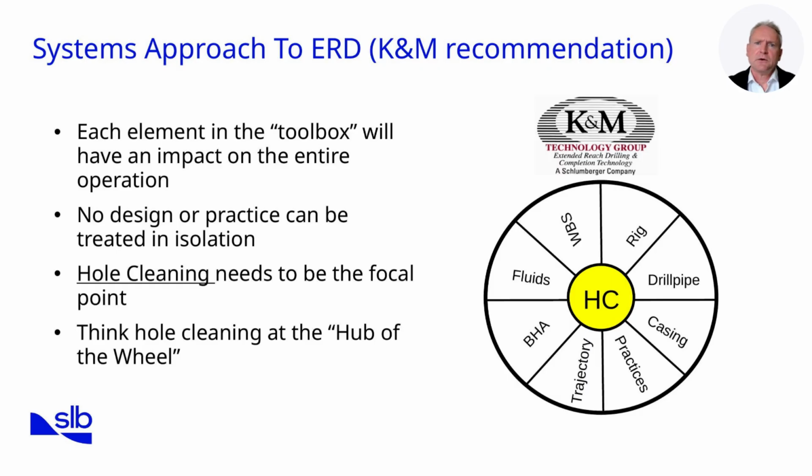A systems approach is the key to success in extended reach drilling. No single design element or operational practice can be treated in isolation. Instead, every tool and technique must be considered as part of an interconnected whole. Think of hole cleaning as the hub of a wheel. Every other element, from mud properties and pipe rotation to casing and completions, connects back to hole cleaning. If hole cleaning is neglected, the entire system begins to break down.